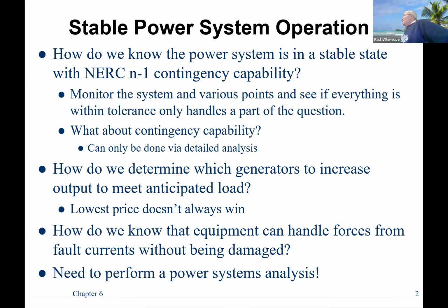And one of the things is because these are electrical systems and stuff happens, right? You got long transmission lines that are exposed to the environment and, you know, you can't always protect those. We've got to assume worst case that we can take any single piece of equipment, and I don't care what that piece of equipment is, any piece of equipment has to be able to be taken out of service, and the grid has to be able to survive that. It may not be in a happy space, but it has to be able to survive taking out that worst piece of equipment. And that's what's called N-1 contingency.